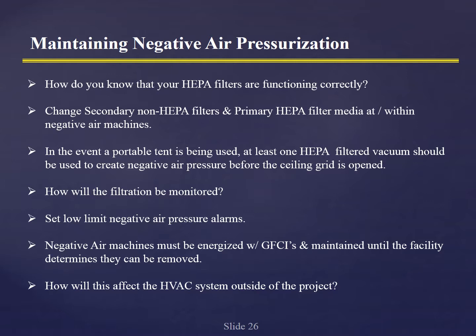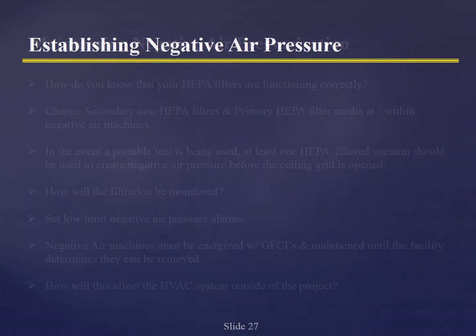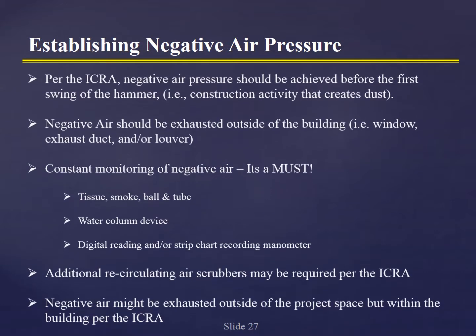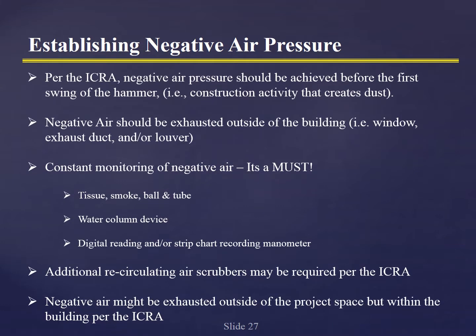So, you know, these things, it's simple sort of, I guess, physics, and we need to think about that when we're doing these projects. Again, establishing negative pressure, you've got to do it per ICRA. Again, it must be achieved before the first swing of the hammer. Negative air should be exhausted outside of the building if possible.